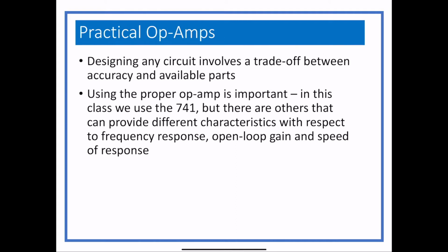In here, we use the same op amp for everything. The 741 is a reasonable op amp. It's not expensive. It works for what we do. It has some limitations as far as speed and frequency response, but other than that, none of those things matter in here, so we use that. They're inexpensive, so when you blow one up, I can always just go get another one and give it to you, and it's all good.